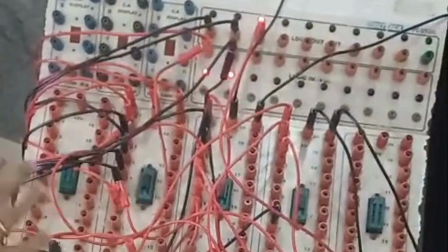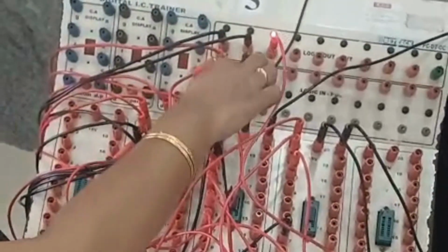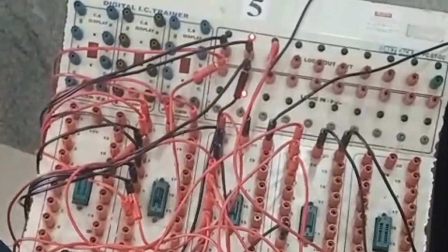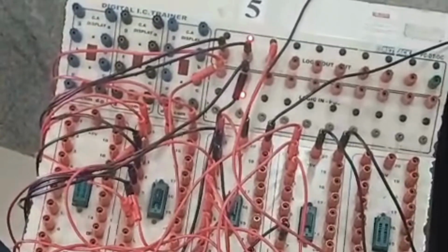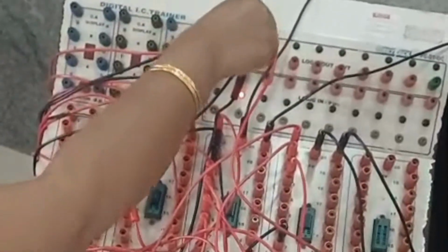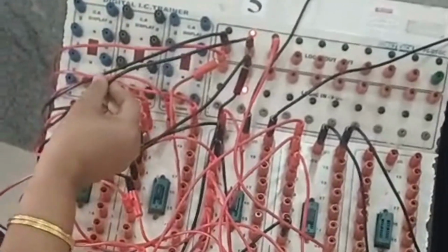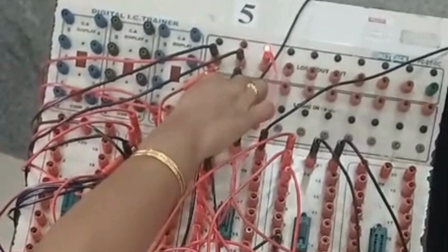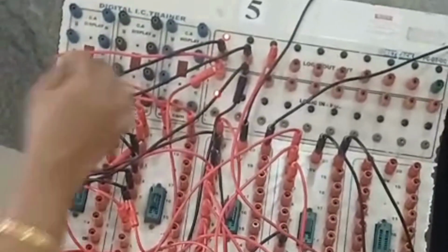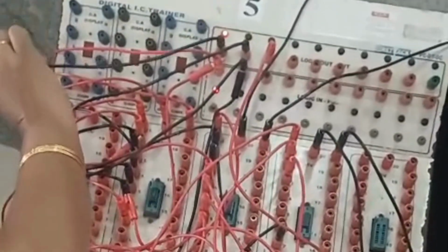Let us check the circuit for the other 2 combinations, A greater than B and A lesser than B. Let us first go for A as 0, B as 1. A is equal to 0, B is equal to 1. It clearly states that A is lesser than B, and the middle output we have kept for A lesser than B. So it is having a value high. The next combination is A is 1 and B is 0. A is 1, B is 0 means A greater than B. So this is the output variable that we have taken for A greater than B.